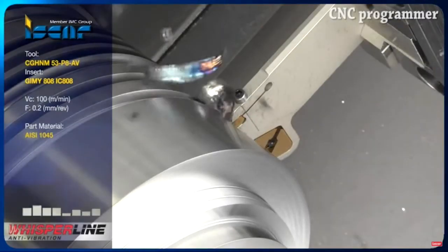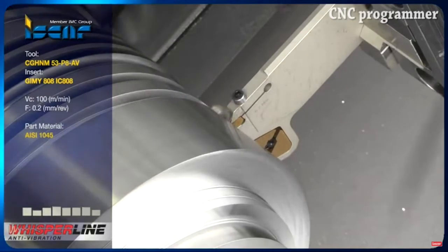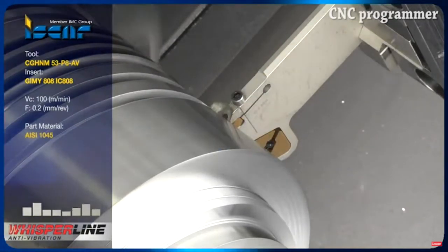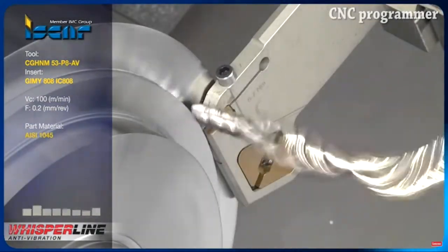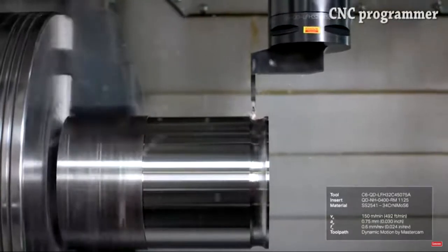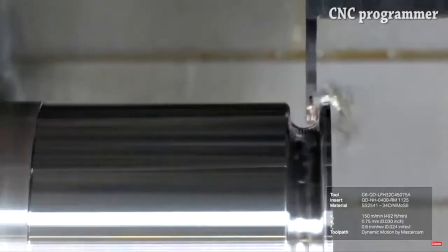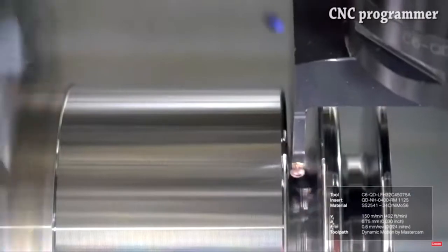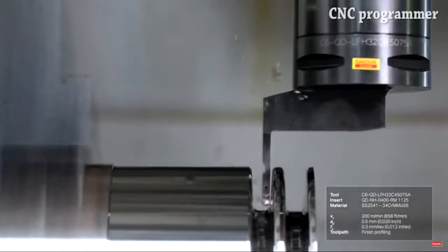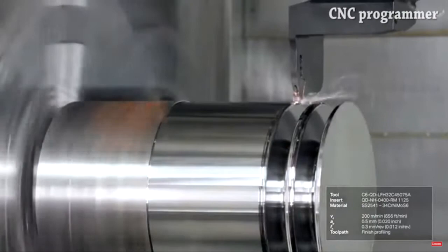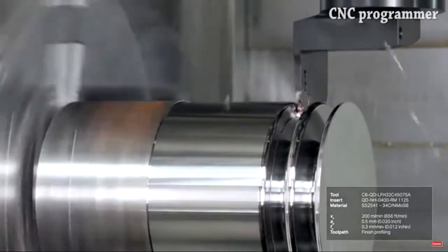Here's an example of an external grooving tool, just doing grooving, not designed to cut the entire part off. And here's an example of a grooving tool that's designed to turn also. It has a circular insert in it, so it can cut side by side, but the profile is a curvature. So these are pretty handy for replacing several different tools, and you don't have any transition marks between one tool and the other.